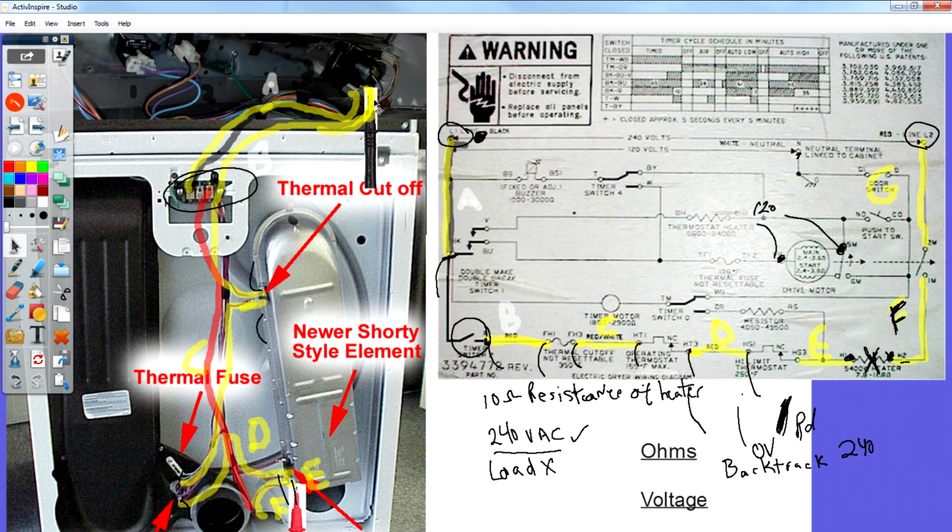So you guys will have the opportunity as you get towards the completion of a specific appliance and have that opportunity to troubleshoot the problem, not just test the part and see if the part's good or bad. I want you guys to learn this process of troubleshooting. Again, I know it's a little foreign to you because you haven't had your hands on the machine. Some of you guys really haven't even used meters yet. And one thing is you have to learn to use your meter and have to learn to trust the reading that your meter is giving you when you're making a test.